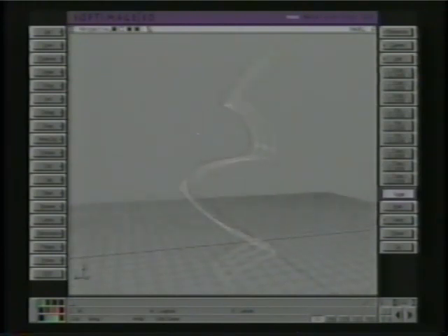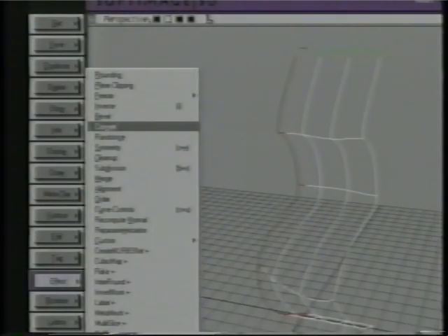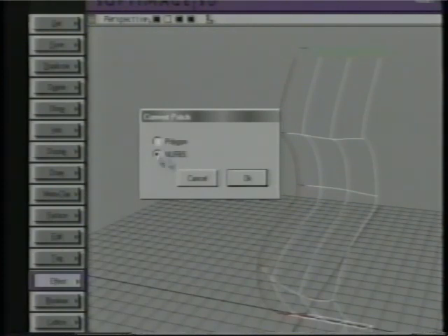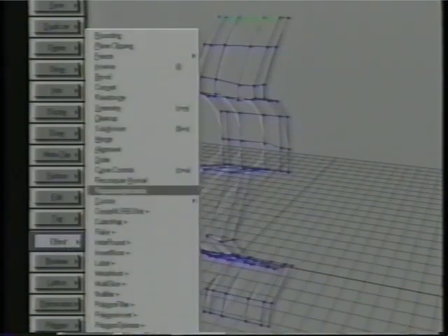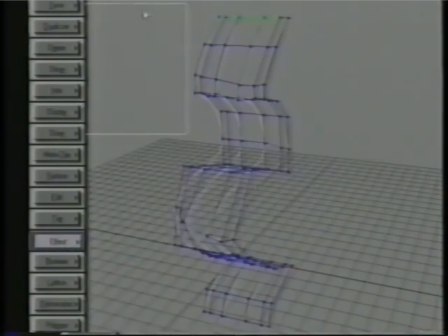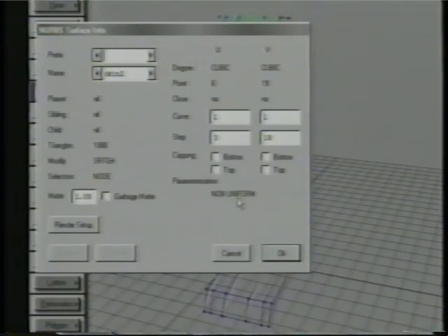All the actual lines are going to be hard edge, and that's because they're not just one control mesh row. The actual curves of the surface are stuck together so that they look hard. And you can verify this by going into Effect, Convert, and choosing NURBS. Now that it's NURBS, you can use Effect, Reparameterization, and well, let's cancel that. Go into Info Selection. We can see what it is already, and of course it's non-uniform, which is the default.